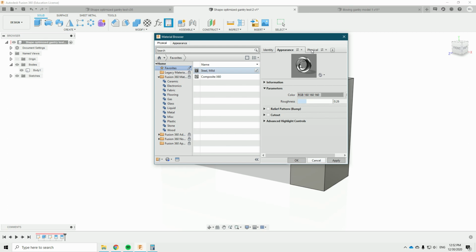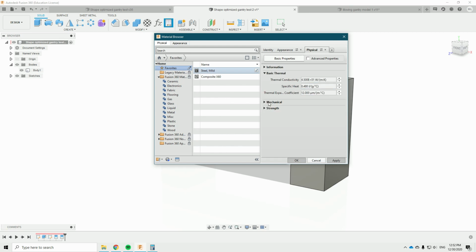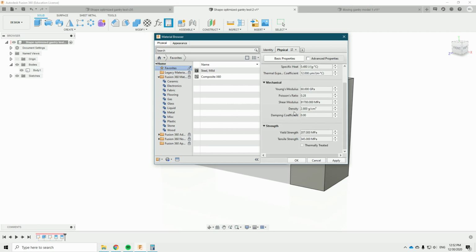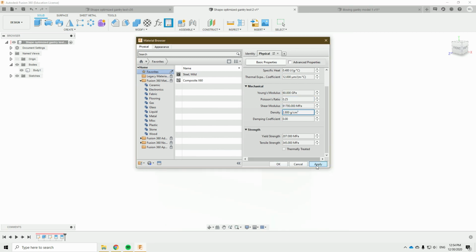You can change the appearance, and what we will be interested in is the mechanical properties, and you can change the stiffness right here and Poisson's ratio. I looked up a quick number for Poisson's ratio, and that will be 0.25 for epoxy granite. For my composite, I have entered the following: a stiffness of 60, and we'll actually just change this to 25 and we will be good. Let's go ahead and press apply.